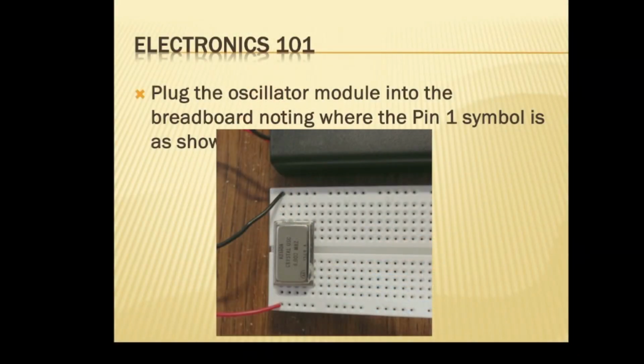This stuff going up and down here, as opposed to a perfect square. Correct. That's how it's done. That's it. Okay, so let's turn you off. And then we're gonna put a filter on it when you get to that. So we're gonna take this output out of here. We're gonna build a little filter circuit up here, come out of the filter, and we'll see it smoothed into a sine wave. I'll help you with that.